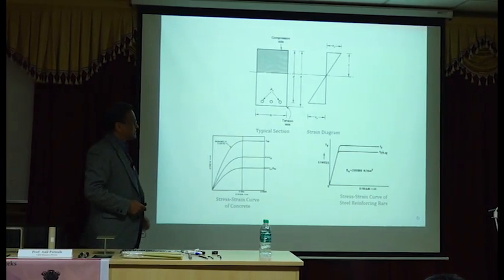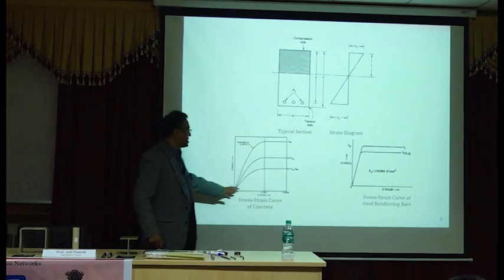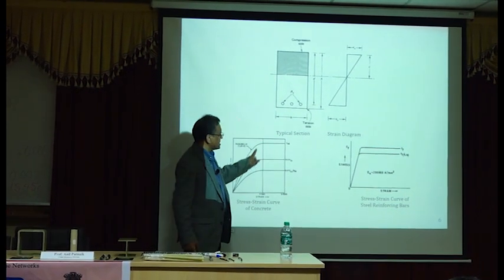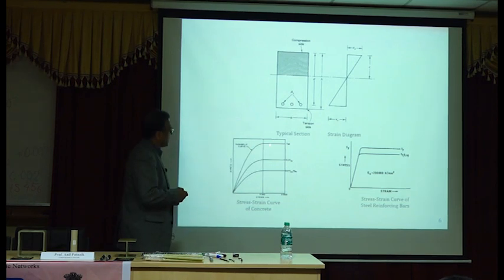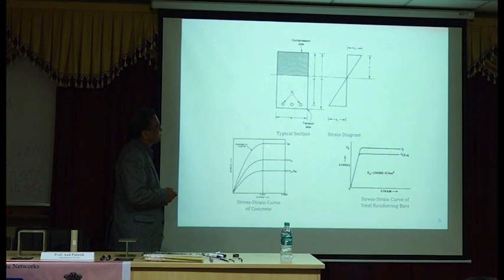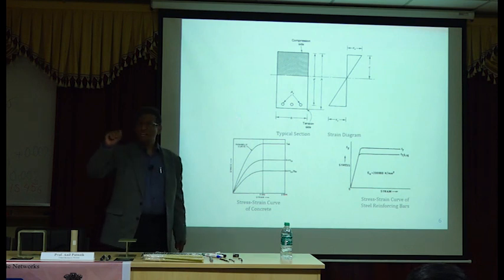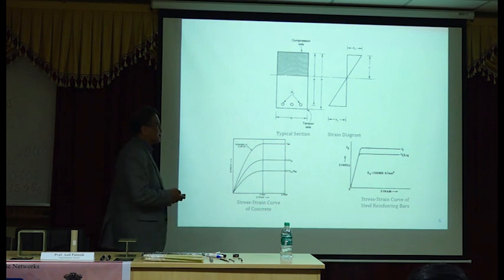This is what we have in IS 456. What do we have? We have a stress strain diagram, which actually should have a falling branch here, but this approximation simplifies our analysis. So they just make it a straight line. Up to 0.002 you have parabolic variation. Beyond 0.002 up to 0.0035 it is a constant stress for any strain between 0.002 and 0.0035.